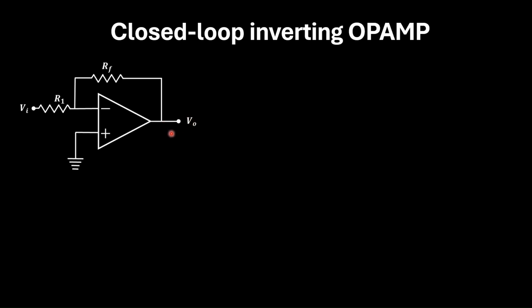So this is the expression of the output in the case of closed loop non-inverting op-amp. Now in the given circuit, the output is connected to the input, so it's a closed loop, and the non-inverting terminal is grounded and input is applied to the inverting terminal. So this is a closed loop inverting op-amp. Now let us try to calculate the output of this. So using the golden rule, the same current will be flowing in this part, and this voltage is 0 volt, and I will take this one as Vx. So we can write Vx is equal to 0 volt.